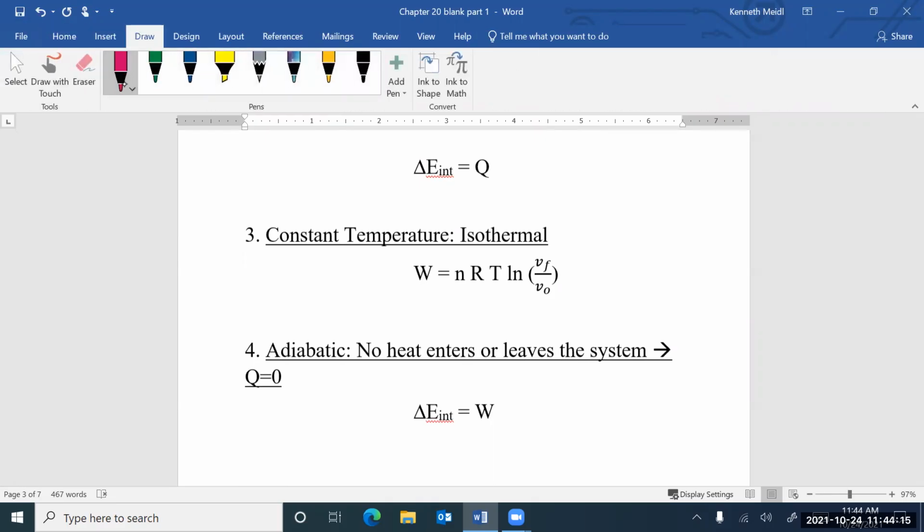So remember the first law, that is the conservation of energy, says the change of internal energy of the gas is the heat that you put in, Q, subtract out what work you get out of the gas, and whatever is left over is still locked up in the gas. How's it locked up? In terms of temperature. So you get it hot, it expands, it makes something move, you get some work out of it, and the difference is still accountable.